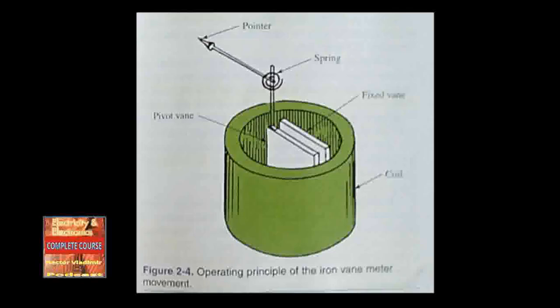An indicating needle is attached to the moving vane. The needle is equipped with hair springs so that the vane must move against the spring tension for accurate readings. An applied voltage causes the current flow in the solenoid and creates the magnetic field. The moving vane is repelled against the spring according to the strength of the magnetic field. The needle may indicate either voltage or current. It is calibrated for the magnitude or average size of the applied voltage or current. When the iron vane movement is used for a voltmeter, a solenoid is commonly wound with many turns of fine wire.